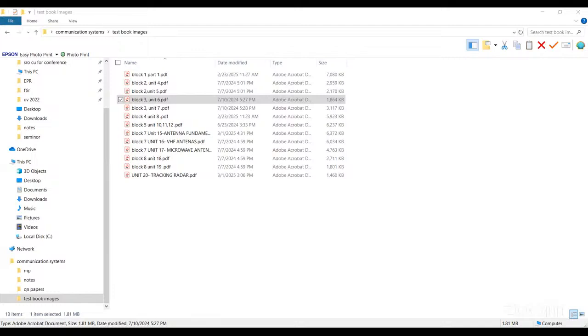Next, what is PB? Coupled power in the backward direction. Why are we getting the backward direction? When there is a split between the 2 waveguides, after coming down, it may move in the backward direction or in the forward direction. The backward direction is represented with PB. Forward direction is represented with PF.